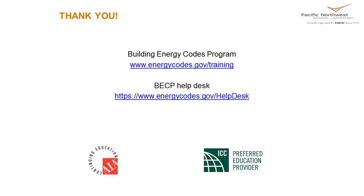All right, I'm going to take one more question, Jennifer, and I think then we're just going to have to call it the end of this webinar. Okay, so the last question then is, if you are adding a second floor to a single-story dwelling, what do you enter for the floor value for insulation? Well, if the floor becomes an interior floor between two conditioned spaces after the addition or the alteration is complete, so post occupancy or whatever, post alteration, then you don't show it.